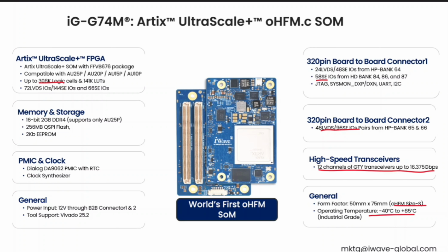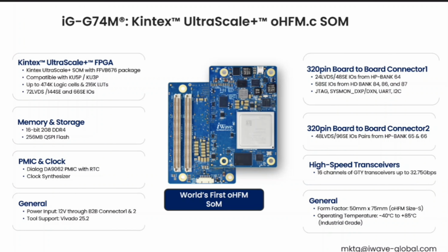from -40 to 85. And if somebody is looking for higher transfer speed, we have a Kintex based SOM where we can support 16 GTY transfer up to 32 gigabits per second. Also you can note that it supports 475K logic cells.